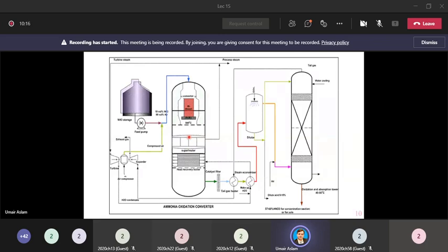Firstly, in this superheater, and then in this heat recovery boiler. So from this line, water goes into the lower section of the reactor. Firstly, it passes through this heat recovery boiler where it gets the heat from the product species, and then the same water goes into the superheater where again it will get the heat from the product species.